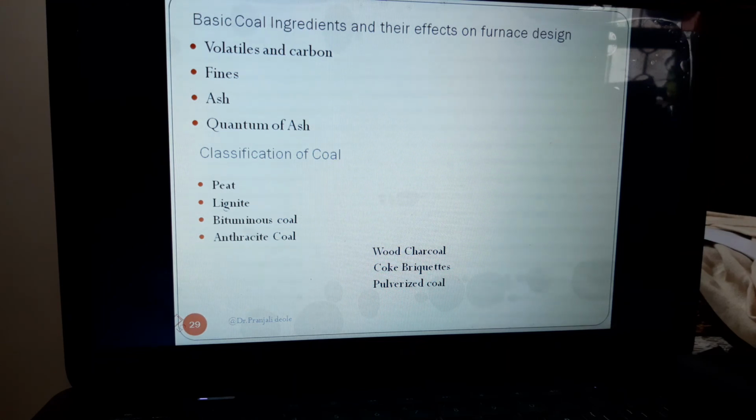The another type of coal is the briquette. So it is produced from finely ground low grade coal actually by the molding operation. The coal powder is mixed with a suitable binder and it is pressed together to form blocks or briquettes. The binding material may be pitch, coal tar, crude oil or clay. By this method, the heating value of the low quality fuel is improved.